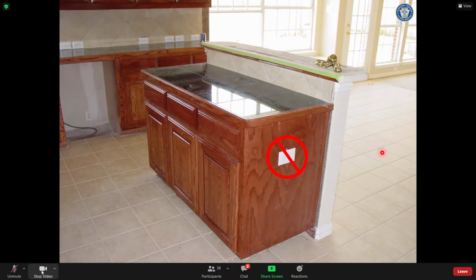Okay. That's why I asked. I don't think there's a rule in the code that says thou shalt not put this receptacle right here. It just says if I have a backsplash, I can't locate a receptacle under an overhang of greater than or below the countertop. So there's nothing telling you to eliminate that one then? That's what you're saying?